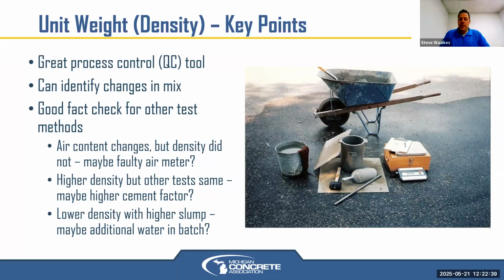Water weighs 62.4 pounds per cubic foot, whereas concrete weighs about 150 pounds per cubic foot, roughly. I think as engineers, we learned that in design school as a good rule of thumb for concrete. Water is less than half the density of concrete. So if it's got lower density and higher slump, more water in the mix, those are two keys that maybe we got additional water in that particular batch. So again, it's a good quality control tool, very highly recommended.